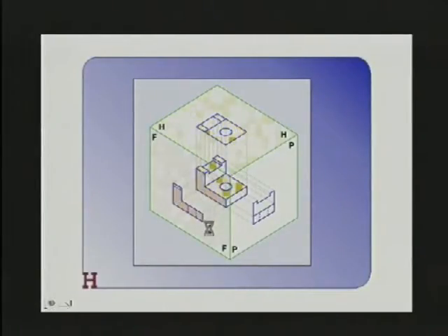Let's project this object onto the frontal reference plane. And you see here, I haven't drawn all infinitely many of them, but I've drawn the key projection lines that are perpendicular to the reference plane through every point on the object, and we get the image we call the front view, which is actually the image projected onto a frontal reference plane.